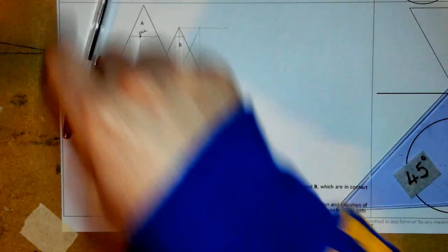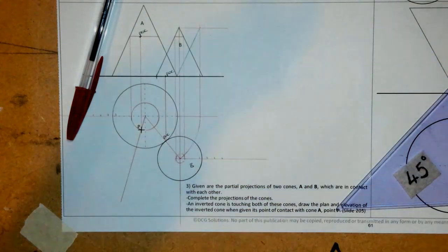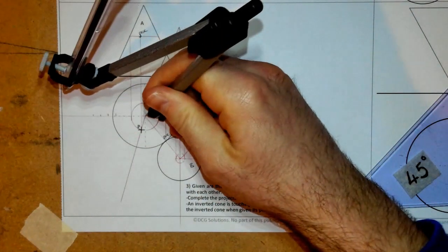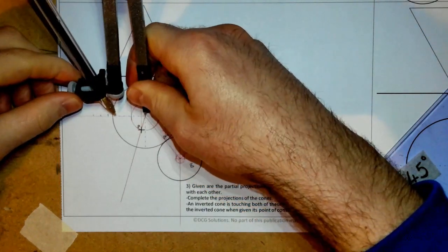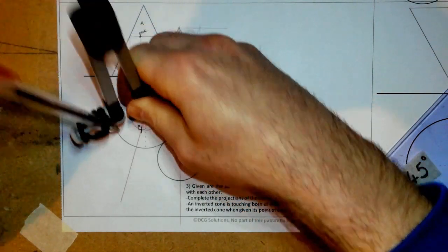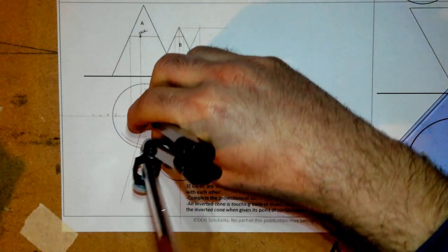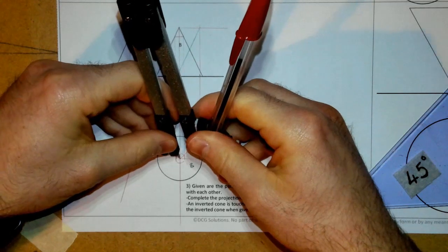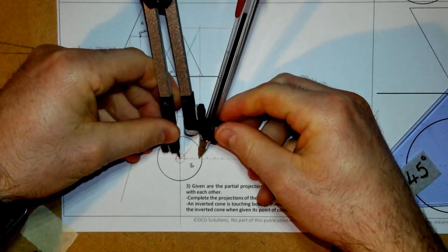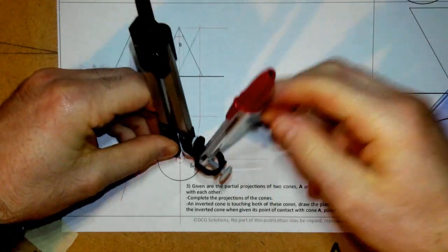Okay, so the same thing here now. What we're going to do is we're going to rotate around with all of those until they match up with each other and get the locus of a line that's going to be equidistant from both. Okay, so at the first one, at the 10, it's going to be somewhere inside in here, and then the exact same with the next one. I'm going to do it from here to here. There's our line.